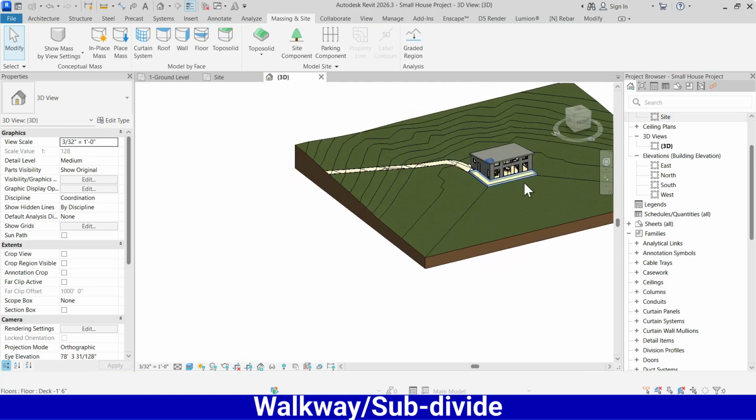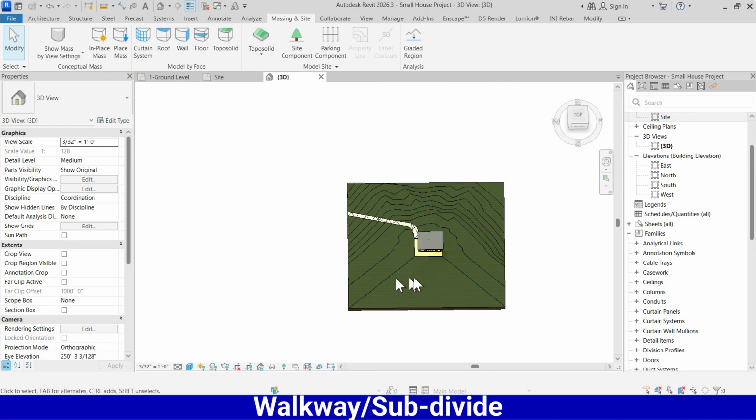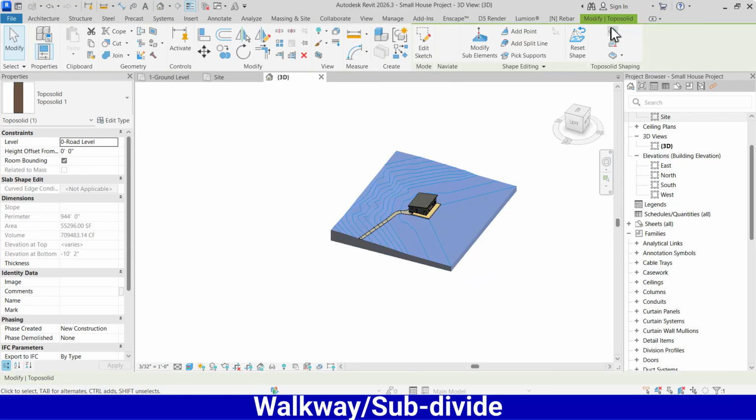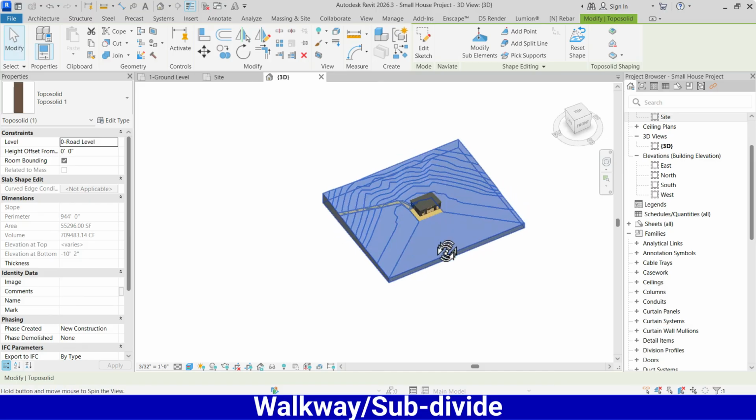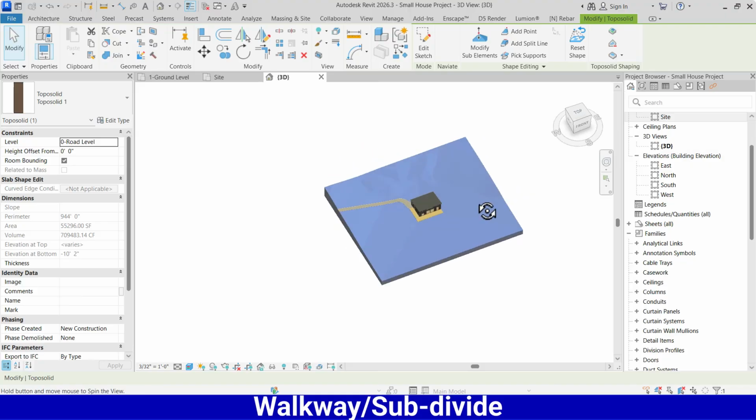Our path is ready. If you want to create a road, you can create it with a similar method like subdivide. Click it, make it subdivide and duplicate the Toposolid and make it asphalt and create the boundary of the road. So simple.